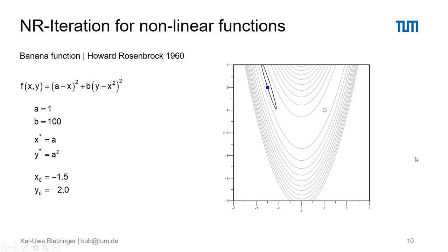So what we're doing is that we determine the stiffness matrix at this first iteration step, and we determine the out of balance load vector, and can by that construct the quadratic problem as on the previous slide, which we minimize in one step. Here's the minimum point. That means the lowest point within this quadratic pot, and then we just repeat. So for the next step, we determine again a quadratic problem with elliptic contour lines, where here is the minimum of this next step.